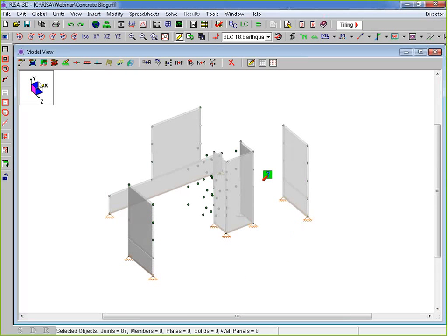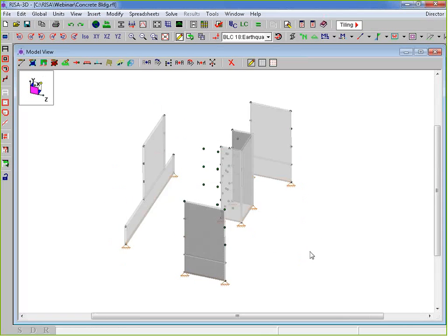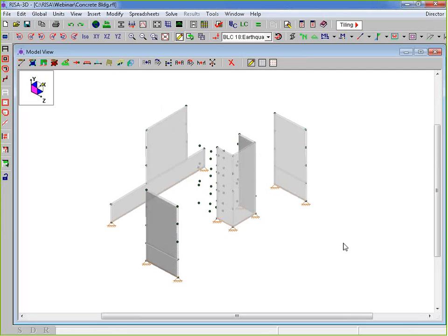Now, one of the things that is important, right? We were talking about why we would do this in Risa Floor versus Risa 3D. This is all interior, exterior, and this is going to be in regards to our out-of-plane reinforcement. The only time your out-of-plane reinforcement comes into play is when we're doing lateral loads or things that are going to be affecting that out of plane. So in Risa Floor, we're not going to really know too much about interior, exterior, and really where you're going to be concerned is in Risa 3D, whether this happens.